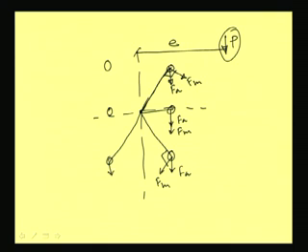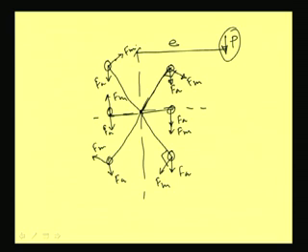So, accordingly it will develop. For this we will see F A and F M, and for this it will be F A and F M, and for this it will be F A and F M. So, what we are seeing is that all the rivets do not get the same forces; different rivets are exerting different magnitudes of force.